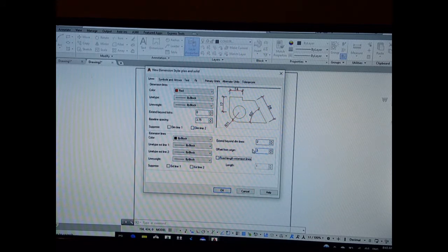And to see how it looks at the same time, you can press tab. What tab does, tab adjusts it instantly. So to me, that seems a little bit too much. So I'm going to change that to probably 2. 2, tab to see what's going on. So 2 seems good. If this was a building dimensioning, I would let that offset distance be probably 150 or 100 millimeters. I like to make it 150, sometimes 200 millimeters. Alright.